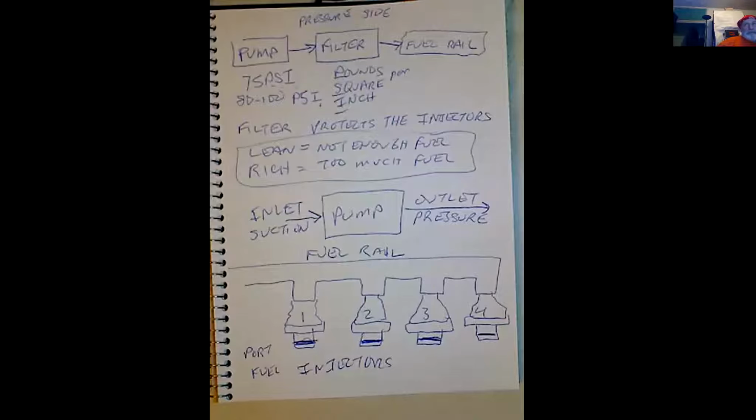Remember from our lesson from last week how we talked about burnt valves? A burnt valve is always what kind of valve? Exhaust. Unless the adjustment is so far out of whack that the valve never hits the seat. Why do we adjust valves, Michelle? So you have clearance. What is clearance?